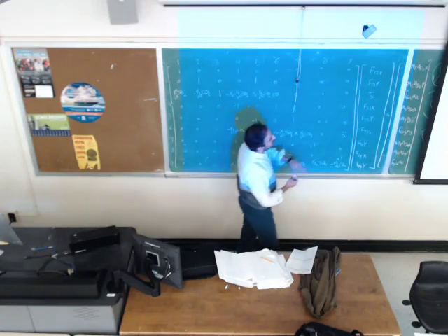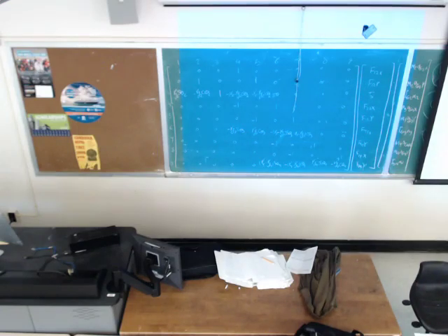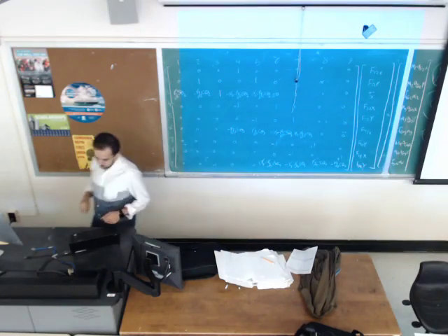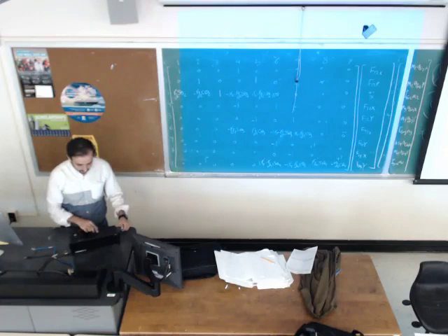Now, after you find them, if I ask you what would be the shaking force applied to link 2, shaking force is F12. We can say the square root of F12x squared plus F12y squared. What would be the shaking force applied to the link 4? So you can do that.